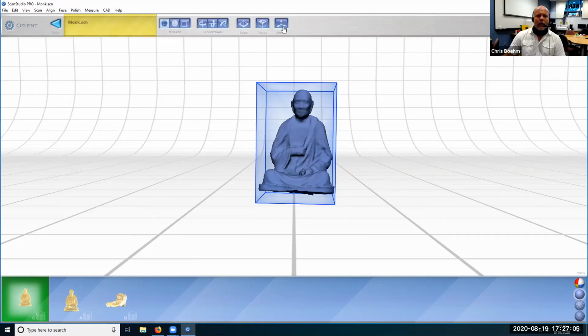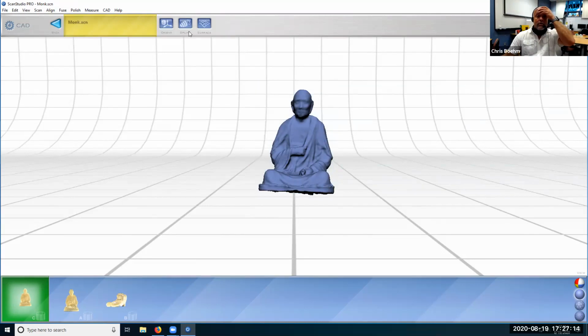And we could even place an origin if we wanted to, let's say, right at the center of it. And so those are some additional options. We could even create some spline data and some surface data right here in this software, or we could do it in the RapidWorks software, which I'll show you very quickly after we have completed this model. So lastly, let's go ahead and send this to output.